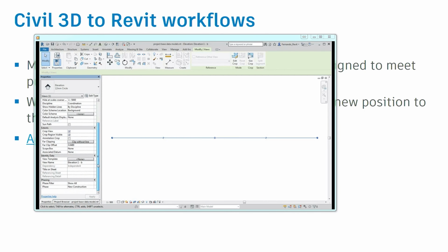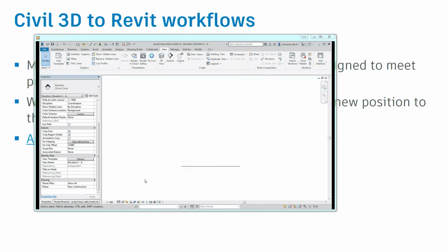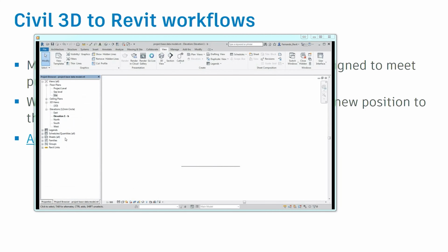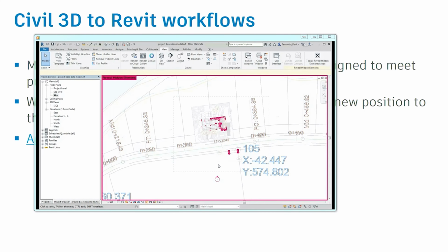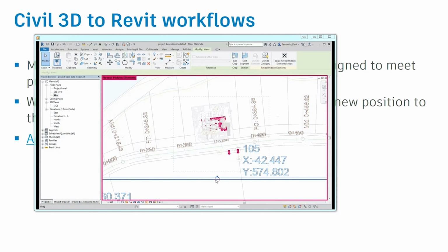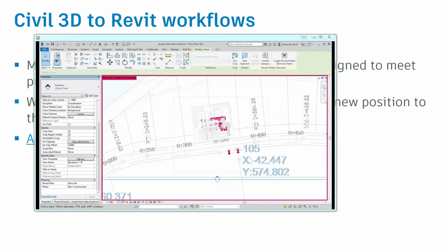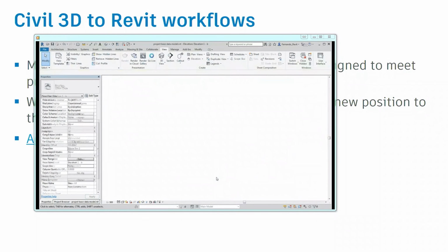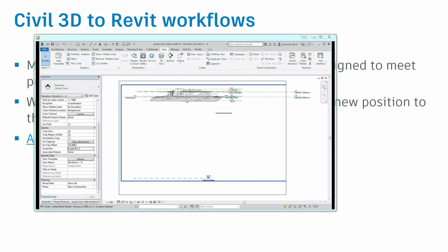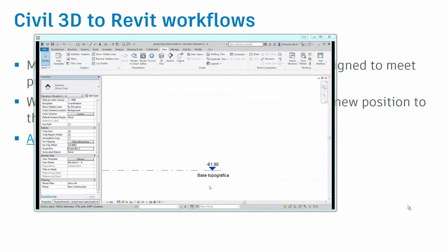Okay, this is the continuity of the process here. So I'm establishing the elevation view. I had no reference yet, so I'm not connected to a scope box. That's why it gave me much more trouble to review. And the extent of it was not yet associated with a scope box. That's what I'm going to do now. I connect the elevation with the scope box. And when I jump to the view, now it's showing the depth of the scope box.